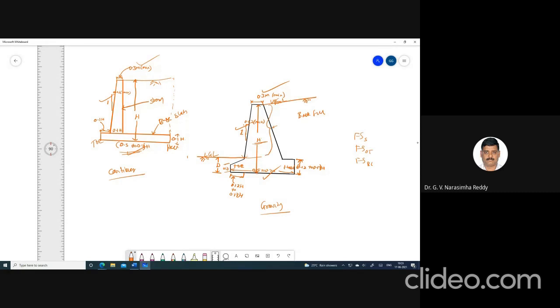So similarly here also you will have the downstream side, and the depth of the retaining wall is D. So here also you need to see this is the actual difference in height, whereas H is, in addition to this, you will have the depth of footing. That means H is equal to the actual height plus D. D is the depth of footing, DF, let us say. DF is the depth of footing, or D, which we are calling. Is it clear?